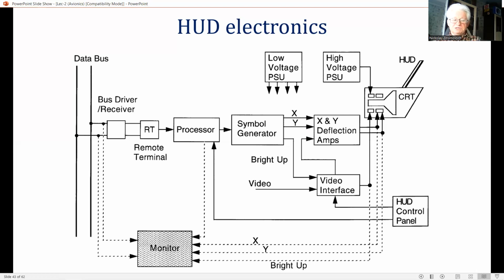The display processor processes this input data to derive the appropriate display format, carrying out tasks such as axis conversion, parameter conversion, and format management. In addition, the processor also controls functions such as self-test, brightness control, especially important at low brightness levels, mode sequences, calibration, and power supply control.